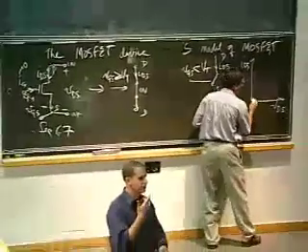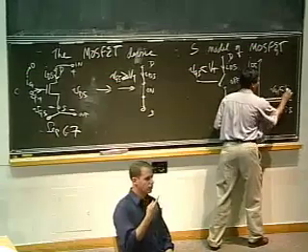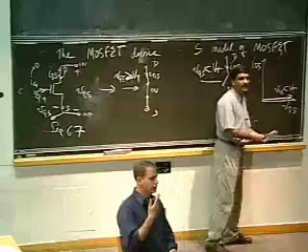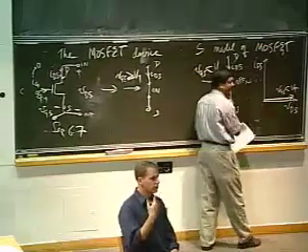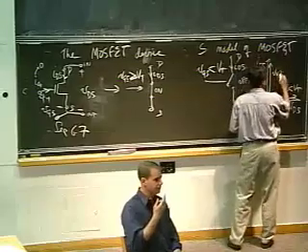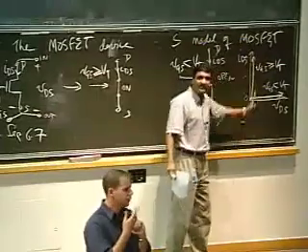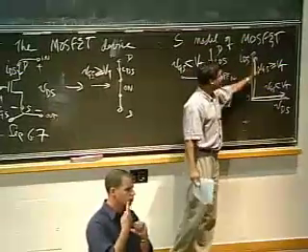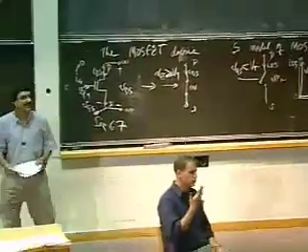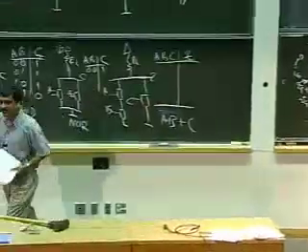So what I'm going to show you is that if VGS is less than a threshold, then this behaves like an open circuit. So no matter what the voltage is, the current is 0. Similarly, if VGS is greater than or equal to some threshold voltage, then I get the IV curve of a short circuit where the current can be anything and controlled by external forces like in any short circuit. Okay? So let me show you on the screen.